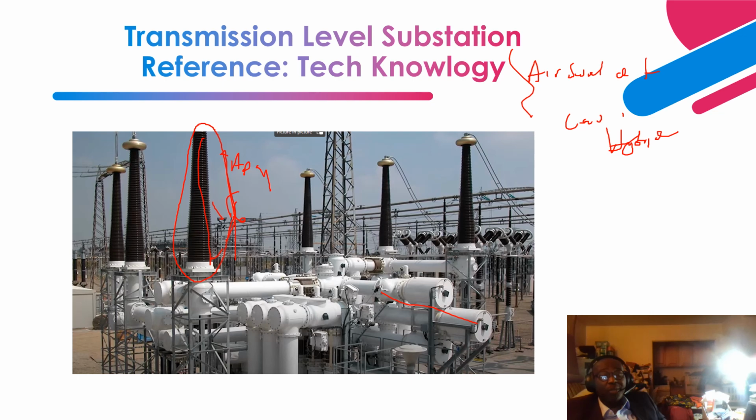as an insulating medium. Inside this is SF6 gas as an insulating medium. Inside this is your bus arrangement, filled with SF6 gas as an insulating medium. On top of this one is a grading ring. We call it a shield ring or grading ring. Let me explain to you why we utilize that.